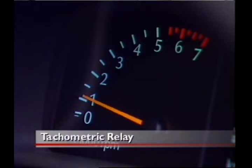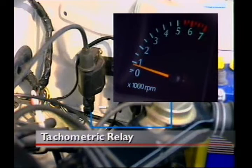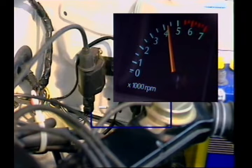A tachometer is used to indicate engine RPM. It is normally connected to the negative terminal of the ignition coil. The pulses from the ignition primary circuit are then used as an input to operate the tachometer. At idle speed, the frequency of the pulse is steady. As the engine speed rises, the frequency of the pulse increases as the tachometer indicates.